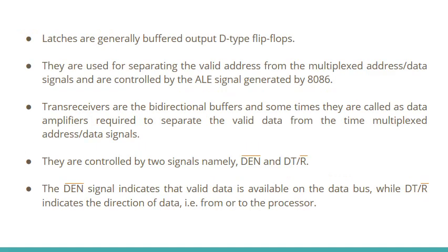The latches are generally buffered output D-type flip-flops. These latches are used for separating the valid address from the multiplexed address/data signals, that is from AD15 to AD0, and these latches are controlled by the ALE signal, that is the address latch enable signal.